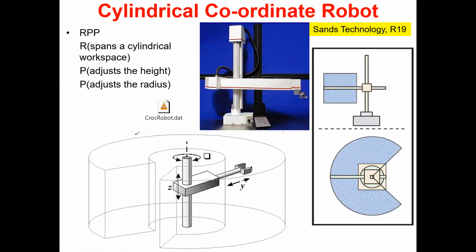Now you probably are beginning to understand that the particular type of robot manipulator that you need to use depends on what you really want to do, right? You have to look at what is the job, what is the task, what is the activity, and then what is the most appropriate manipulator to do the job. If you can do the job with a fewer number of degrees of freedom, go for that. For example, if you can do the job with a Cartesian manipulator, XYZ, which is the simplest and probably the cheapest to purchase, go for that. But be mindful about the limitations of the manipulator, right? If the limitations are going to restrict your operation, don't go for that. Think about a different type, say cylindrical or spherical, whatever.